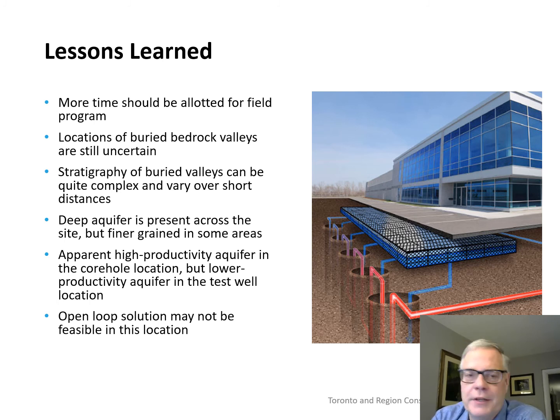We also learned that even though we spent a lot of time with the Oak Ridges Moraine Groundwater Team and others, City of Toronto, looking at locations of buried bedrock valleys in Toronto, there is still some uncertainty because these are located a fair distance below grade, and a lot of wells simply don't penetrate that deep.